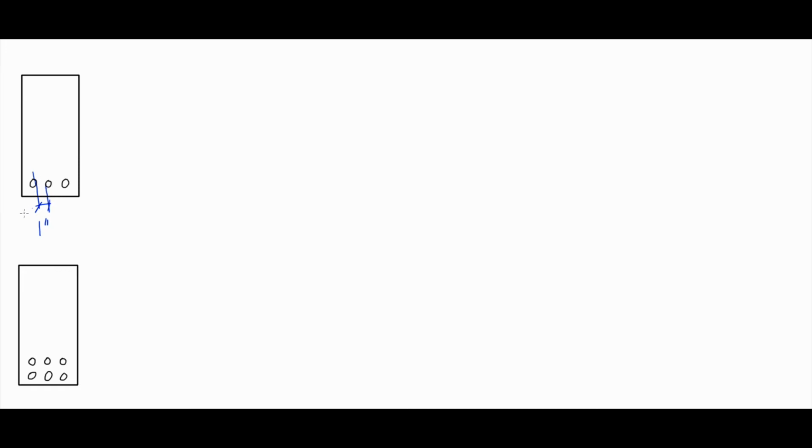Why do we need that? Because this is to allow concrete to go between the bars. Let's assume that we have a bar here, which is a reinforcement, and a bar that is so close to it. When we pour, we have a concrete here, right? And we have a concrete here. Guess what? This area in the middle is overstressed. And what will happen? It will break. And then eventually you will have a reinforcement without any cover. This will, of course, allow the steel to be corroded, and you have a lot of problems. You guys all know about it.